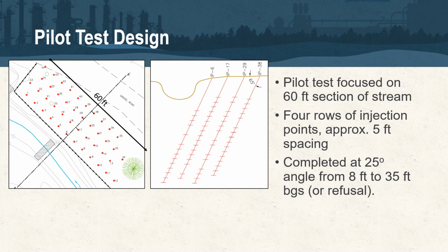So when you're working at, say, 5 feet below grade at an active gas station, for example, because gas stations are good examples since they've usually had historic digs, they've had a lot of investigation work, there's tanks, obviously dispensers, and so there's a lot of things to work around. And if your groundwater's at 5 feet below grade and you try to inject a slurry on a 10-foot spacing, you're going to have a mess, because you have to put quite a lot of volume in to be able to hit that ROI and so on.